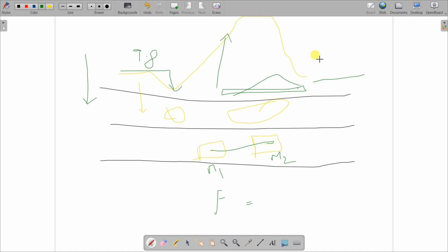Let us discuss how the gravity values are measured. In general, we have three kinds of gravity methods. One is the measurement of a falling body, which means we drop an object from some distance and we measure the distance traveled by the object and the time it took. From that, we get the acceleration. This is one of the methods for identifying the base stations or some absolute gravity places. We'll discuss absolute gravity in the next chapters.